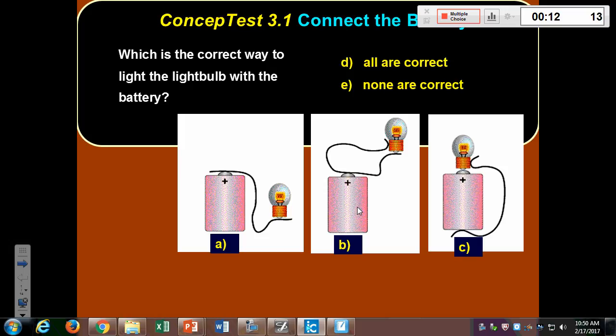I just want to remind you, I pointed this out early on in chapter 2, but when we talk about voltage and current, we talk about them in different ways. We talk about how we measure the voltage across 2 points, or between 2 points, and we measure the current through something. When we're measuring potential, we're measuring the difference in energy between 2 points. That's why we say the voltage across something. And we measure the current as it travels through something. And y'all saw that in lab when you measure voltage and current.